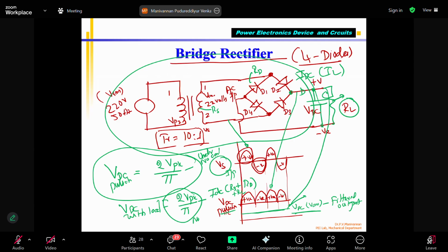What I can do is use thyristors, similar to a diode. A diode is also used for converting AC to DC. Similarly, SCR, silicon controlled rectifier, also converts. We will see that tomorrow, along with 3-phase half-wave and full-wave diode rectifiers, and also how the SCR can be used for half-wave and full-wave rectification, and for driving the motor to vary the speed and torque of the DC motor. We'll see tomorrow. If you have any question, you can ask. Otherwise, you can give your attendance.